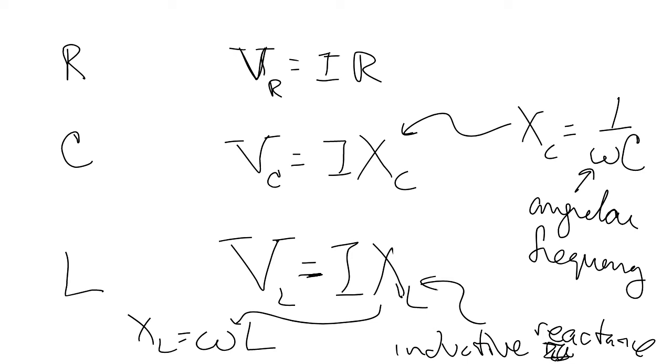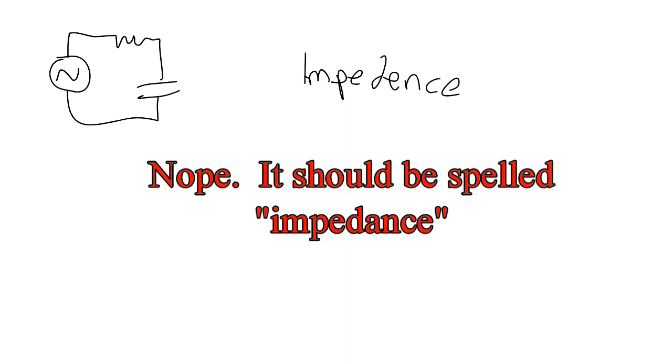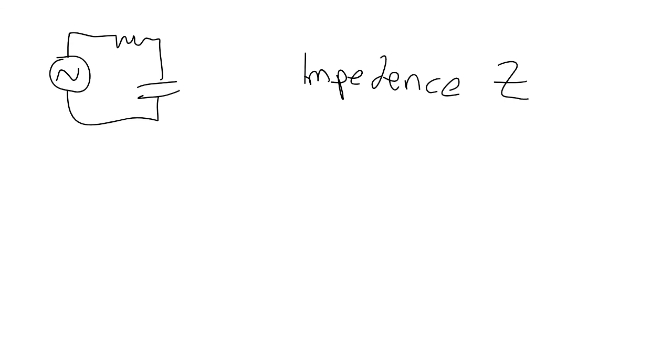And then we went through doing a phasor diagram for slightly more complex circuits. So we dealt with a resistor and a capacitor in series, and introduced the idea of impedance. And I think that's spelled correctly. And the symbol for impedance is Z, and the EMF, or the magnitude, sometimes put a little zero down here, this is the maximum value of the voltage from the power supply, is equal to the current coming out of the power supply times the impedance.